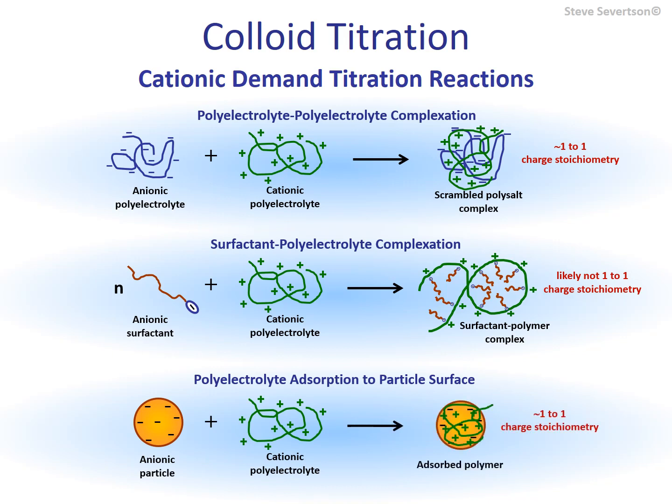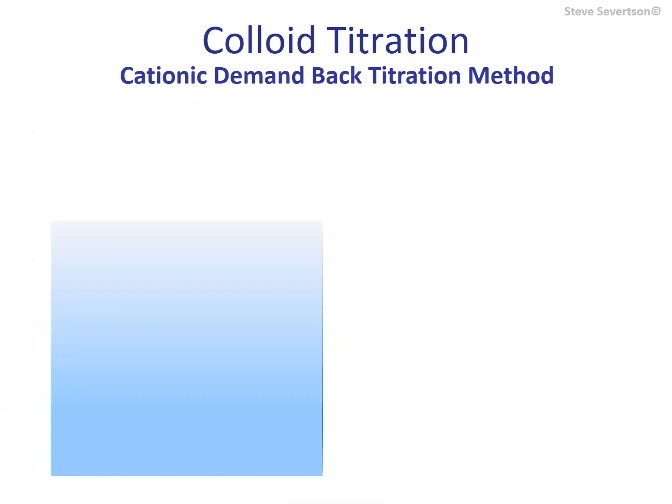The polyelectrolyte should adsorb with a flat conformation, but the solids may possess charge that is not accessible to the polymer. Thus, the polymer used should be representative of the polymers that are actually applied to destabilize the colloid. There are two types of titrations used to measure the capacity a colloid or suspension has for cationic charge, that is, to measure its cationic demand.